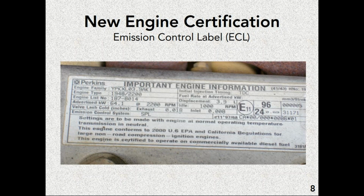And that is on the top right-hand side. You can see there that it's YPKXL 03.9 AK1. That family name has all the information that I need to know what this engine is. The first letter is always designated in a standardized family name as the model year. So Y, if you go look at EPA's list, will be for the year 2000.